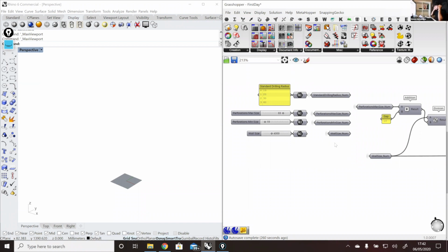Do you have experience with mesh colors changing calculation efficiencies? I'm not sure exactly what it meant here. You can use mesh colors on ShapeDiver in general, when you export meshes from the definition. It's a good way to render something fast, or to have all these color gradients on meshes. In general, it's just less optimal when you transfer data, because you have one color per vertex, so the mesh almost doubles in size, or at least 50% more if you have normals as well in the mesh. That's the only drawback to using mesh colors in the context of cloud applications: the file just weighs a lot more.